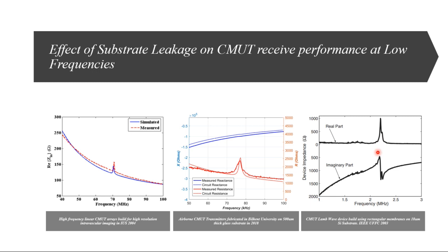That's the fundamental resonance of the vibrating plate, and this vibrating plate tends to couple some of the energy into the backing as well. Okay, in the form of tensile stresses, and you can see that the effect that it creates reduces with frequency. Okay, so the effect is dissipative, so it has to be modeled with the loss on the mechanical side of CMUTs, as can be seen over here. And this loss also affects the quality of your resonance. Okay, if I remove this, I'll show you later on that you will have a very high Q resonance, as you have in air, let's say.